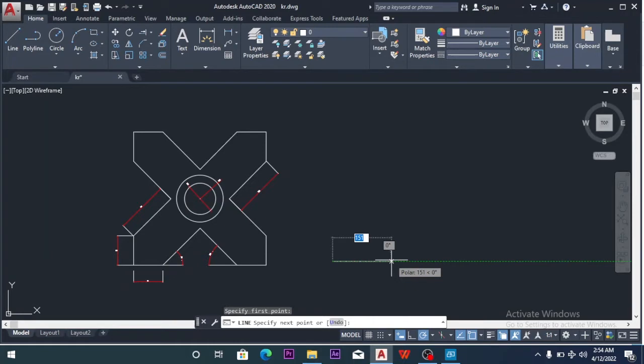in AutoCAD. Remember in the previous class we entered a distance and an angle. So here I want to show you something different. You still enter a distance and sometimes an angle, but in a different approach. Once I click this particular place, I move in the direction I want.